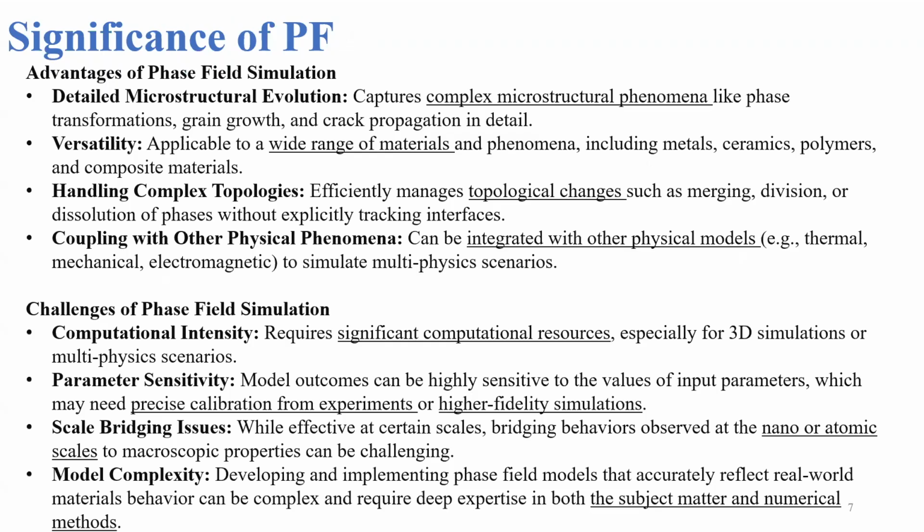So what are the advantages of phase field simulation? Phase field allows us to capture complex microstructural phenomena like phase transformation, grain growth, and crack propagation in great detail. It's very versatile. It's applicable to a wide range of materials, whether metals, ceramics, or polymers. It can handle complex topologies, so topological changes such as merging, division, or dissolution of phases can be captured using phase field, given, of course, that you know the functional form. And coupling with other physical phenomena can also be integrated with other physical models.